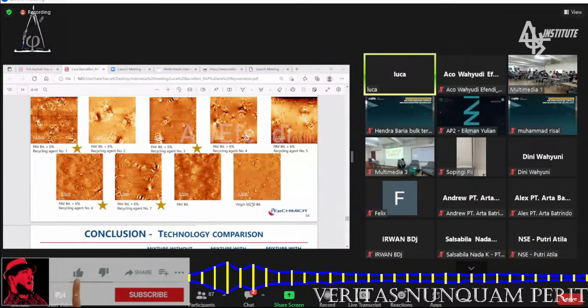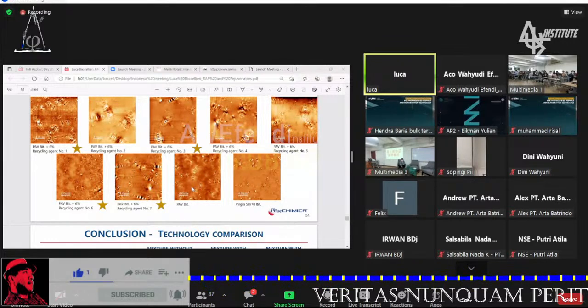It depends on the amount of rejuvenator I'm using, and in that case, the melting point can be around 60 degrees. So the effect of the rejuvenator is that. It is not just that I spread the asphaltene better and dilute it, but the effect is on the dimension and the characteristic of the asphaltene that you are using.